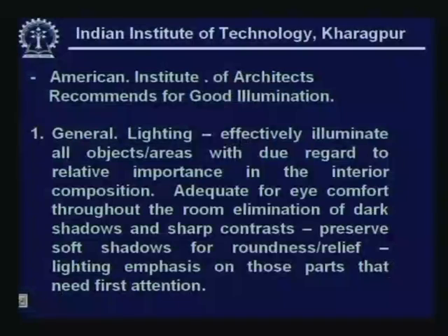So, the first recommendation deals with general lighting, which says it should illuminate all areas, keeping in mind the relative importance of the various parts at a comfortable level, eliminating dark shadows and sharp contrasts, keeping soft shadows so that you are able to perceive the depth, and emphasizing only on those parts that need first attention.